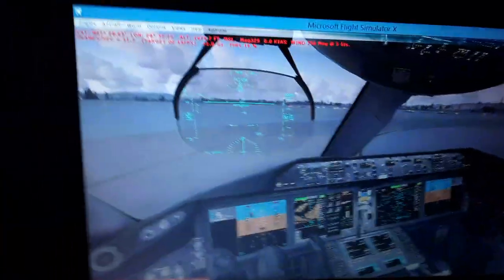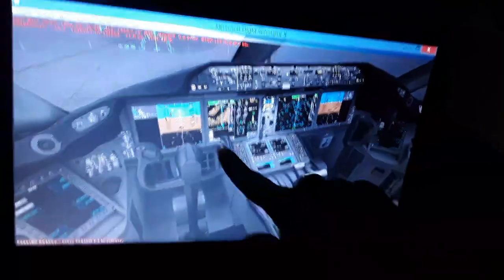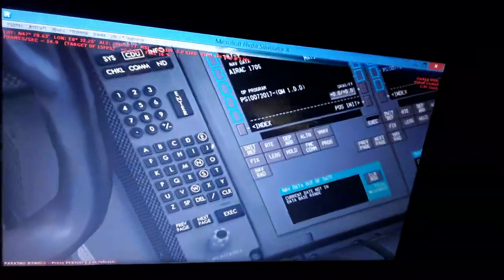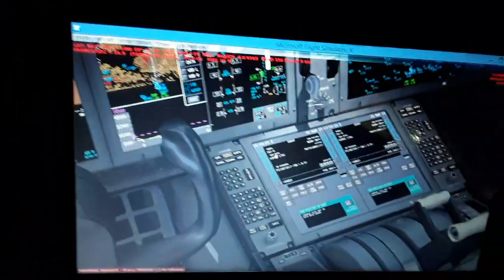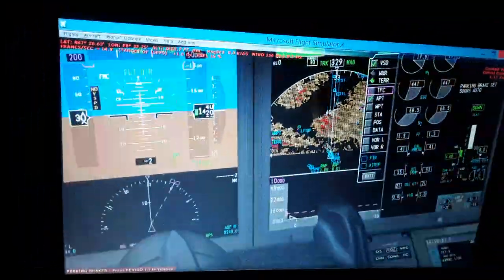We also have the navigation aids, the navaids, VORs, ADFs, and the waypoints, which are horizontal and vertical navigation fixes, and altitude and speed constraints. We're going to have to fly through some waypoints, as you're going to see later. I'm going to use the flight management computer here. I will input all the data for this flight. You're going to be overflying some waypoints. The flight plan will be created here and displayed in the navigation display, also in the HSI, with a purple magenta line.